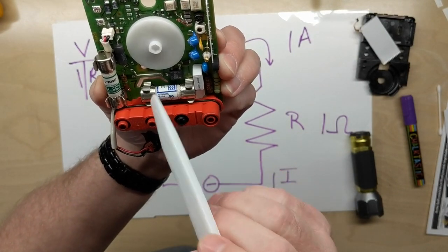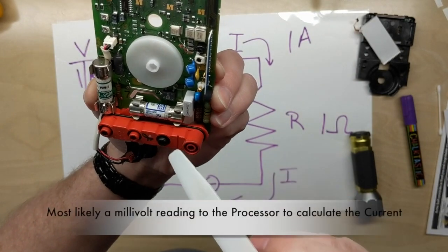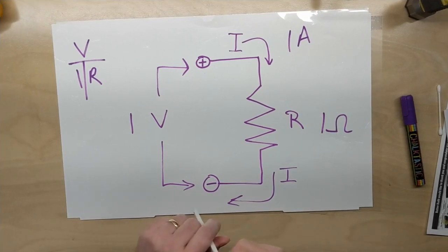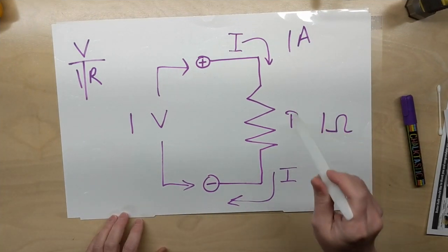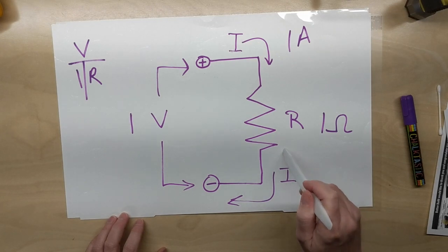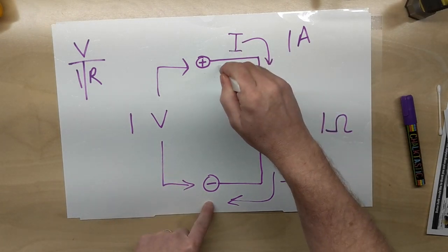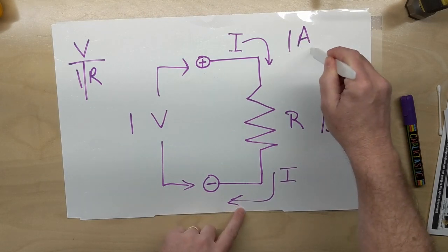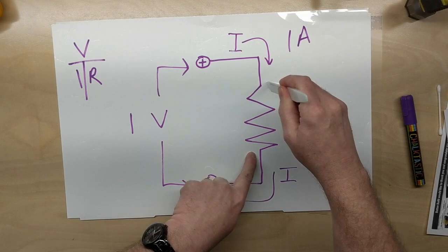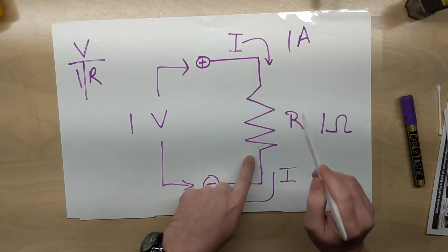It's a low ohms, but we actually get a voltage reading across that resistor. We kind of learn right here how that works. A 1 ohm resistor here with 1 amp is 1 volt. So if we didn't know this current, we could simply read across this resistor and see 1 volt, which would also be 1 amp.